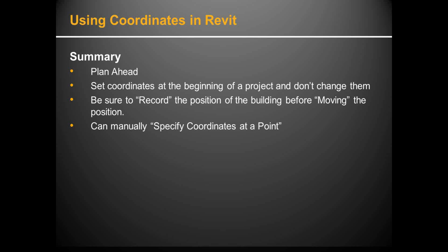And that's going to be kind of a problem. Yes, you're going to lose that stuff. A lot of times having everything linked into a file and getting that coordinate system set up again is going to be nice to do. You can go in and reestablish those coordinates. I think Juliana had one other point, that she's seen architects use this process of putting all the buildings on the site without linking them in. They were just in there as native files. And yeah, that becomes a big headache. One thing you can do, though, is if those things are groups, you can always make a group a link, which becomes a great workaround.